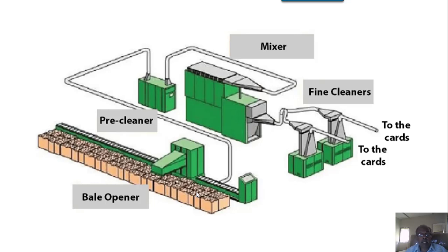How much quantity is to be plucked per stroke of the bale plucker is also set in this panel here. And then the traversing speed is also fixed. It depends actually, but traversing speed normally varies between 9 to 10 or 30, even in certain cases, meters per minute.